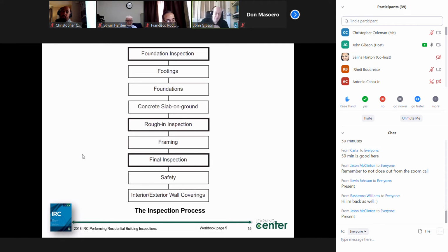So that would be a monolithic pour condition, which has all three of those elements, but it's all done in one monolithically poured concrete, maybe not at the same time, obviously, but it could be depending on the size and the extent of it. We may be pouring that whole thing at once, but normally it's done in a couple of different stages. And our point here is they've grouped all of those similar type items into what's considered foundation